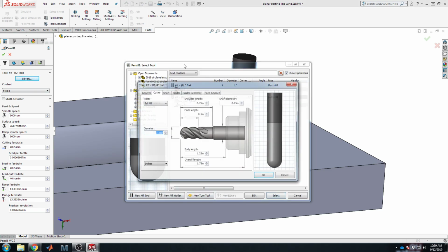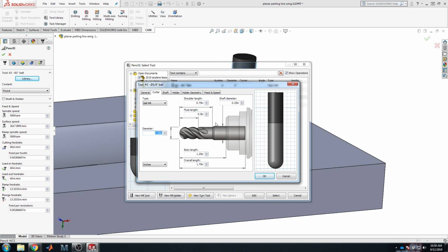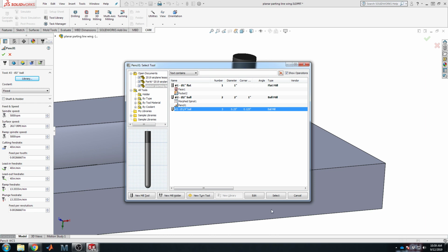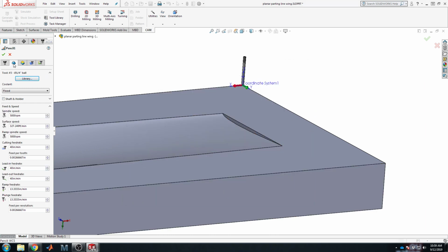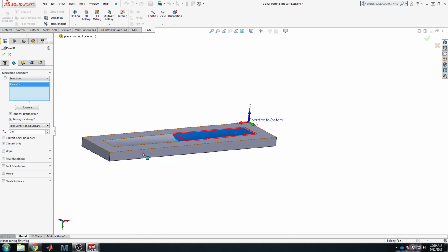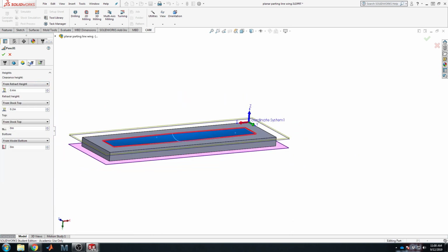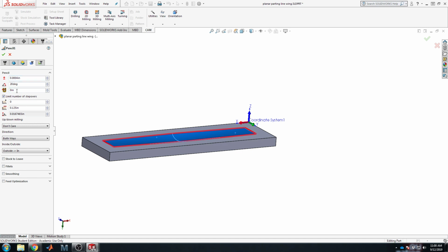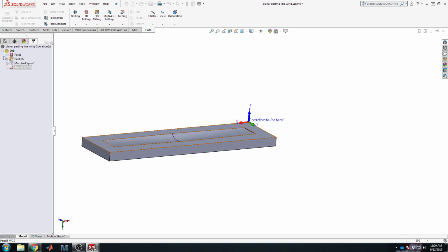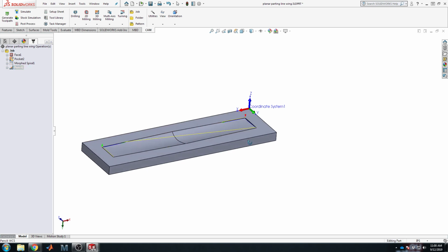So let's actually make a new mill tool. Let's do a small 1/4 inch ball mill, something that's pretty tiny. Give it about a 1-inch cutter. Sure, just defining a tool pretty quickly. So this is a fairly small, fairly cheap ball cutter, 1/4 inch ball mill. So select that. How we're doing the pencil operation. Silhouettes. See if that's good. I'm not going to try to change too many things here. It should automatically detect the edges and go in and remove the remaining material. Yeah. So that's exactly what it did.